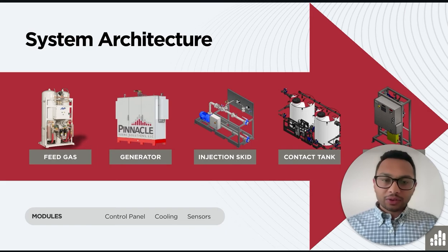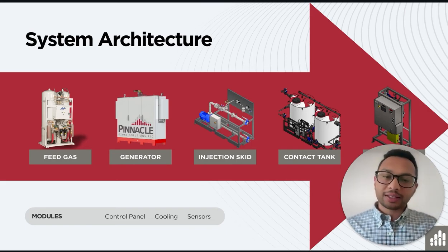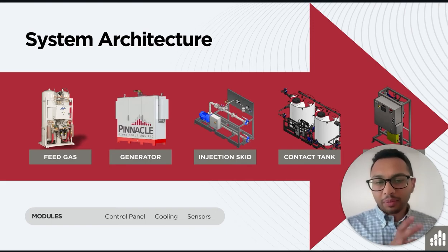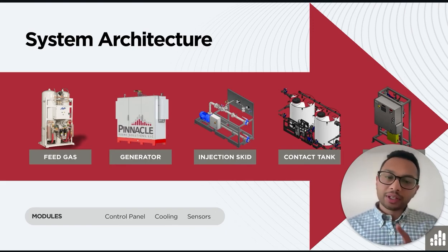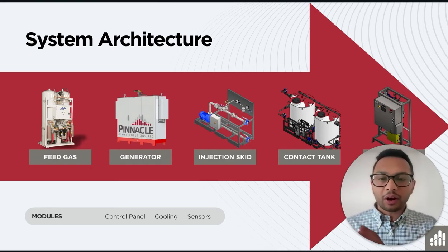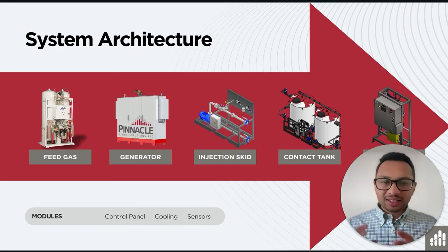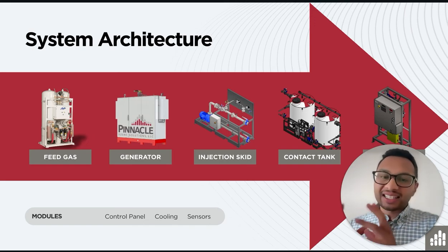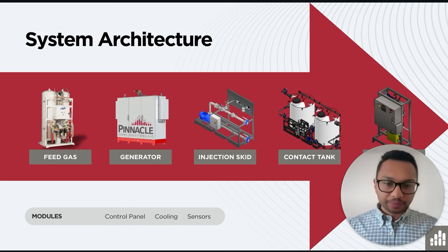Any undissolved ozone gas is then sent to a destruct unit. This prevents any releases to the atmosphere and makes sure that the operators are protected. We use either a catalytic or thermal destruct unit. It depends on the volume and size of the ozone system and the site conditions. These are sufficient and safe ways to convert the ozone back into oxygen.